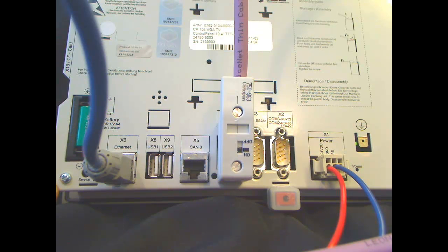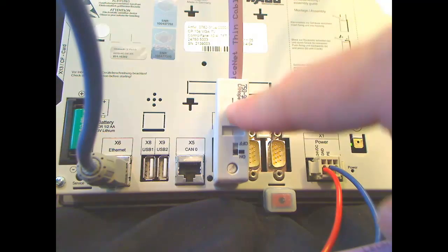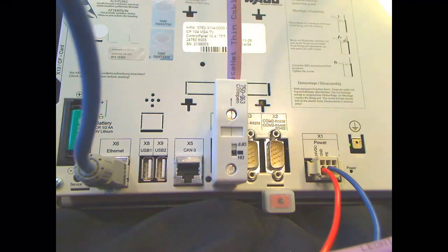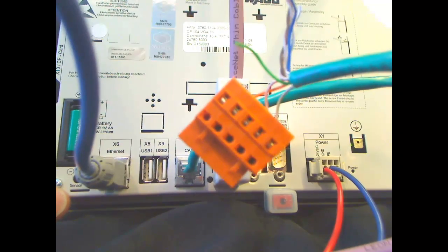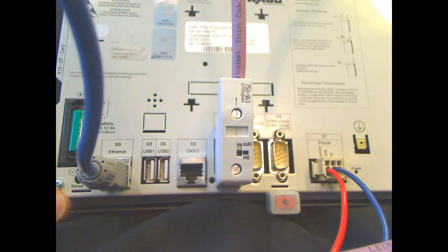Okay, I just wanted to point out quickly the ports on the back that we're going to be utilizing for this exercise. Again, mainly the CANopen ports. You can see this is the CAN0 port, and this one is called the CAN1 port. You can either use the D-sub connections or an Ethernet connection, where you could just plug an RJ45 connection into the panel and then take your standard connectivity to your couplers. In this case, with the WAGO series, we use the MCS connectivity. So either one of those can be utilized for CANopen.